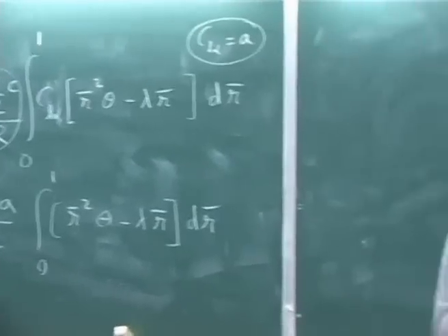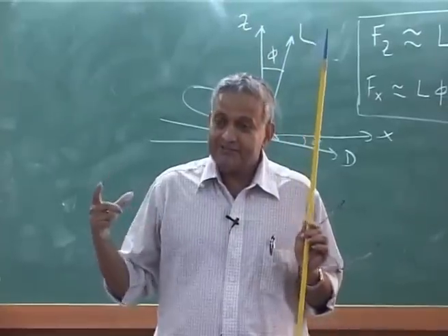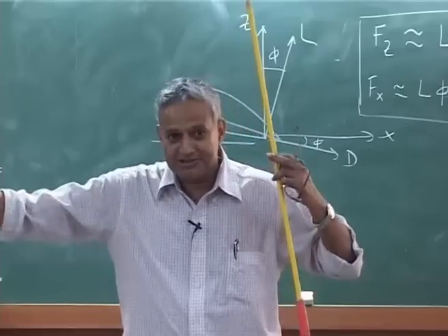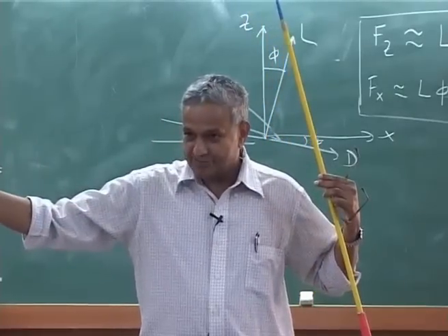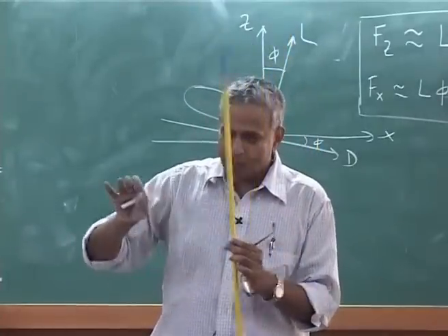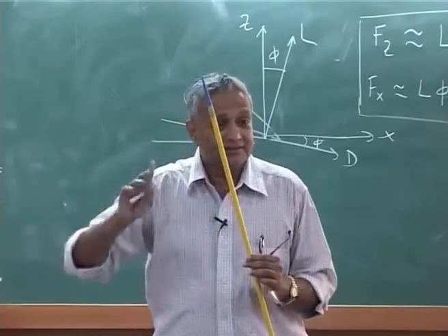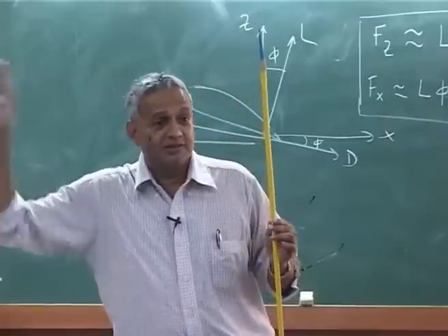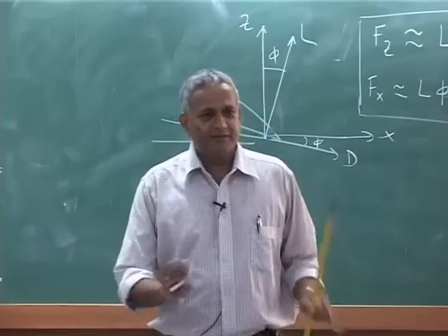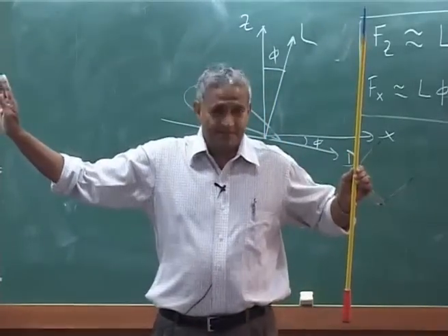I said the pilot gives an input, that is the pilot input he gives at the root, but the blade itself can be twisted. That means there can be a pre-twist in the blade, a geometric twist. That means what the pilot initially gives, and then what is the pitch angle at every cross section of the blade, that you have to take. Now, if it is constant, constant means there is no twist, zero twist.